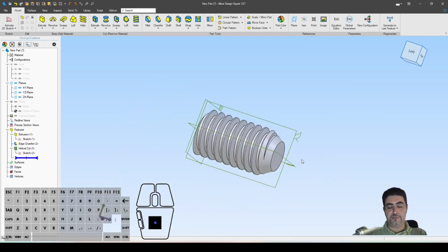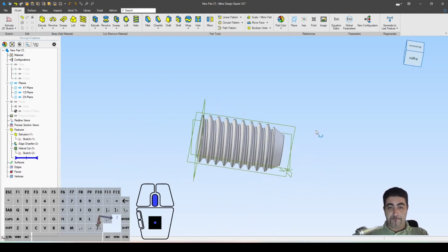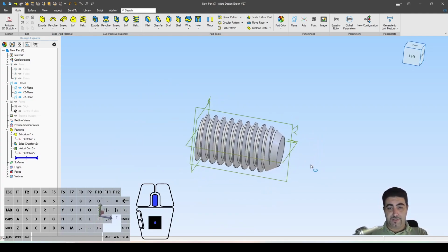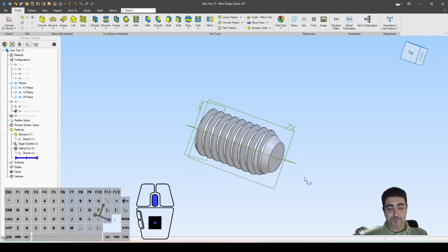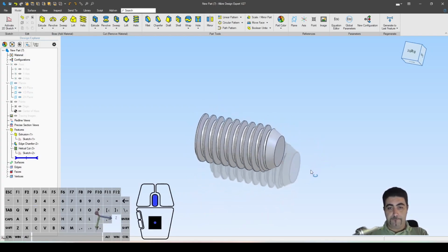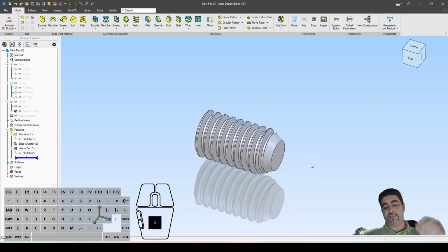Okay. Now we created everything based on the M6x1 thread. So here's a tip, because I fell into that trap so that you don't have to. When you're generating these parts, the generator is going to take the first value for the nominal thread, and it's also going to take the value that was saved for the pitch.